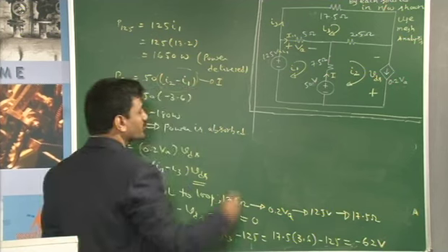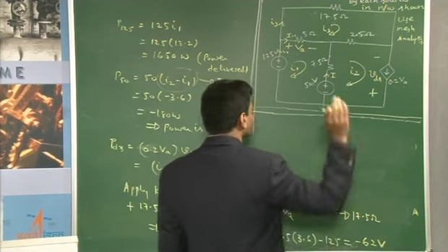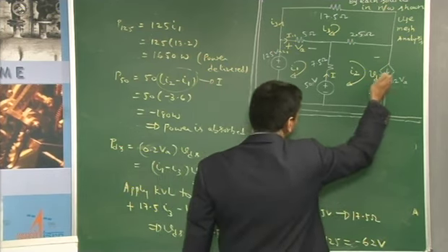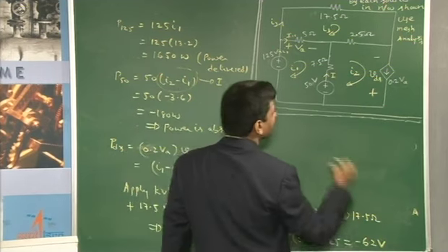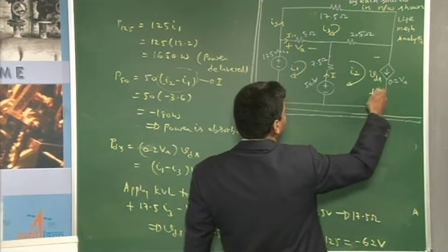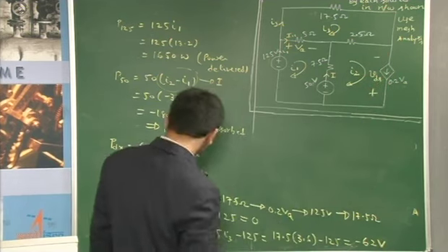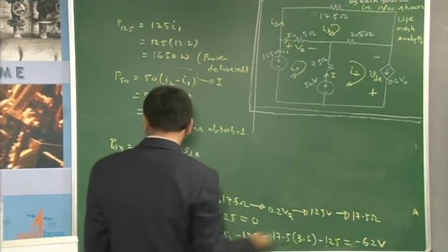So even this is absorbing the power. Because I have told long back that if the current source is delivering the power, always the potential drop across it will have positive polarity coinciding with the arrowhead. But with the value calculated by considering that, you have got it as negative. So the actual positive polarity is at the top, negative polarity is at the bottom. So no problem, we will still calculate the power delivered value only, we will end up with a negative value, that is all.